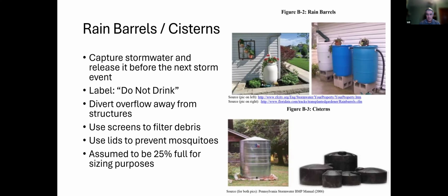Trying to share my screen. Oh, I'm still sharing. Okay. So in this photo here on the bottom, you can see they put it above ground. You can put them below ground as well. You'd have to get ones that are structural, that can resist the pressure from the soil and aren't going to collapse underground. But these things are manufactured for those purposes and are available. Whether you want to install it using a shovel or have somebody come out with an excavator is another question, but they definitely can be used underground.